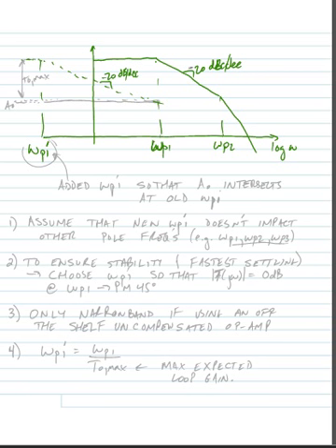What we're going to do is figure out what the maximum loop gain that we're ever going to use in this configuration is, and try and get this maximum loop gain that we desire to cause the closed loop response to intersect at the old or the original omega P1.